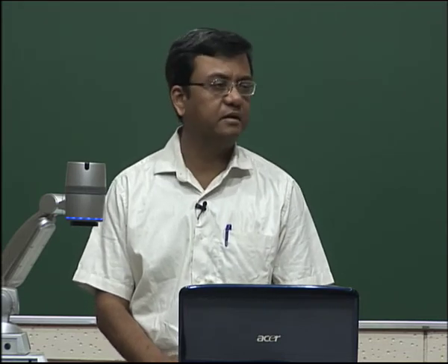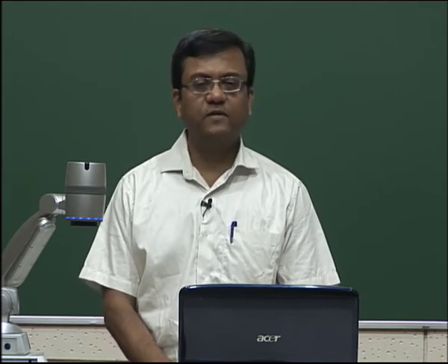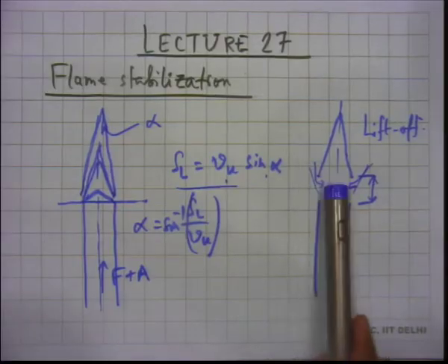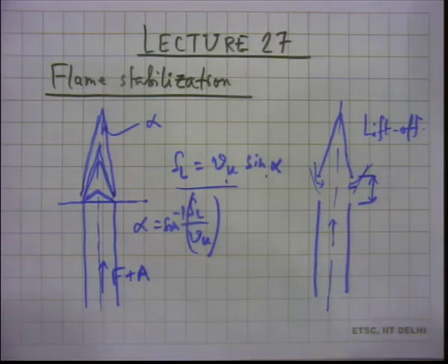So, it is a very delicate flame, and lifted flames also result in some loss of fuel air mixture, because some fuel may go out from here, some air may come in. So, you may not be actually burning the same mixture that you initially intended to. Lifted flames also sometimes are noisy, and lifted flames are difficult to control.